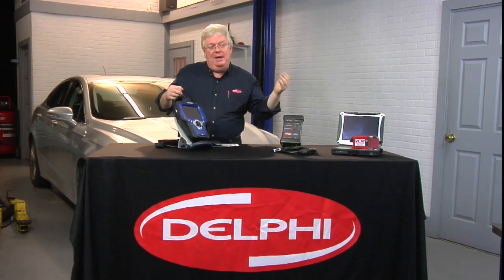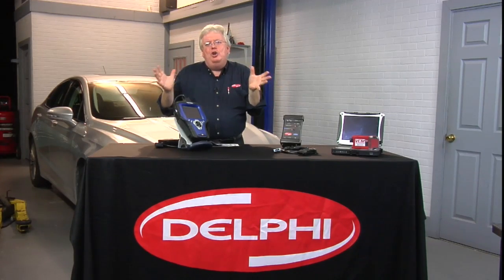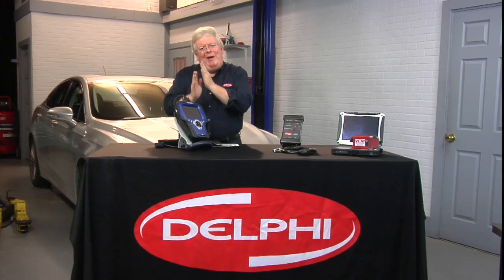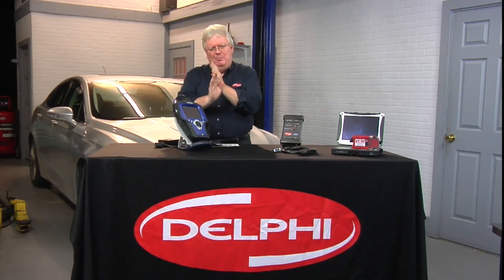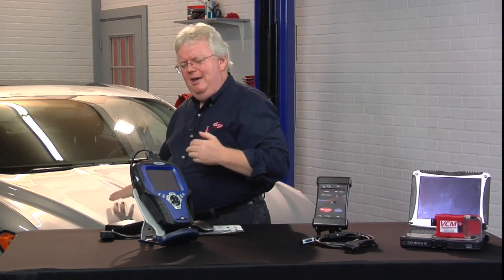Obviously, the improbable we talked about, crazy numbers, no way it could happen. Zeros, it's just not going to be accurate usually. And then exactly at the spec, also very improbable. So I just throw those out. But if it's a number that's maybe doable and you're not sure, then go ahead and clear codes and run the drive cycle and see if you get the exact same number again. What's the chances of all the variations? If you see an engine idling super smooth, but you see RPMs doing this, that's normal, we know that, right? What's the chance of hitting that exact same threshold again? Pretty low in my opinion, so that's what I would do.